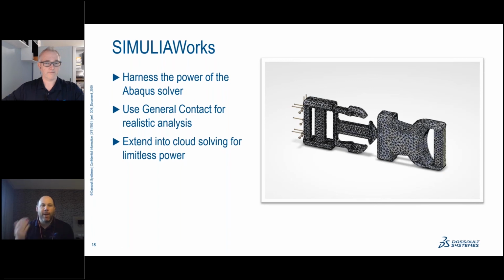And that snap action where it's kind of unrestrained will cause the solver not to converge in SOLIDWORKS Simulation. The Abaqus solver will handle that no problem. And this is kind of a nominal example, but there are many, many real life, real engineering situations where that becomes really important.